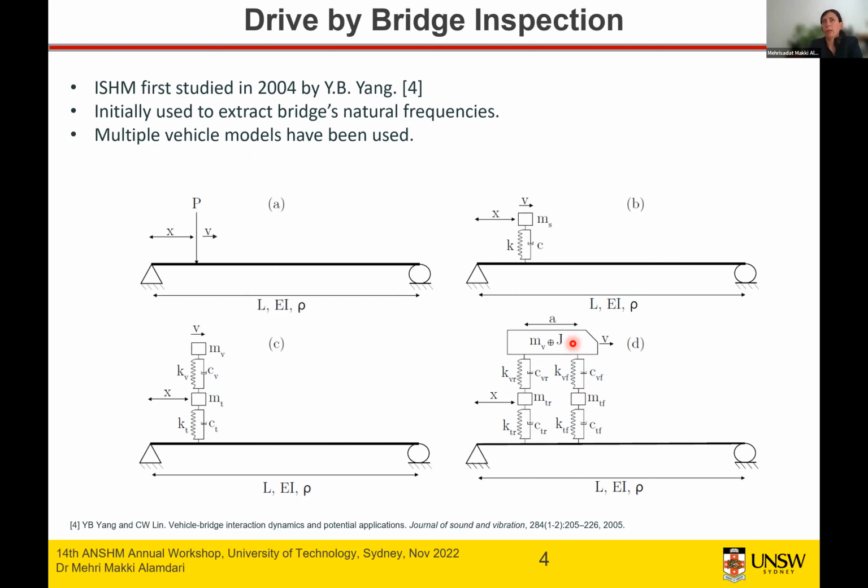But the thing is that in many of these applications and previous publications, it has been shown that yes, it is possible to extract the first few natural frequencies, mode shapes, and even in some studies, the damping information of the bridge purely based on the response of the moving vehicle. Therefore, the analytical and closed form solutions and the investigations based on numerical approaches like finite element show us that it is possible to extract information from the moving vehicle without putting any sensor on the structure of the bridge.